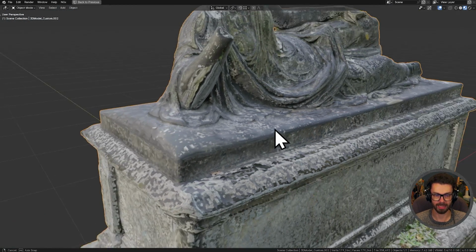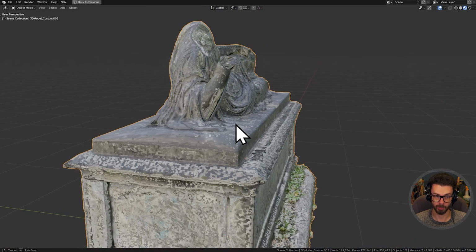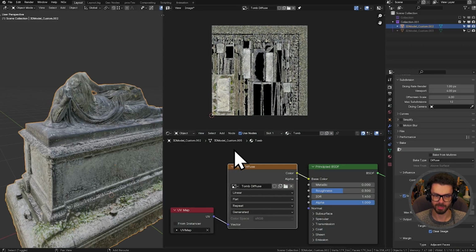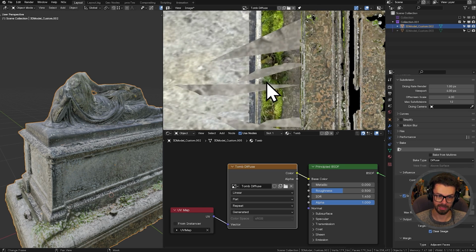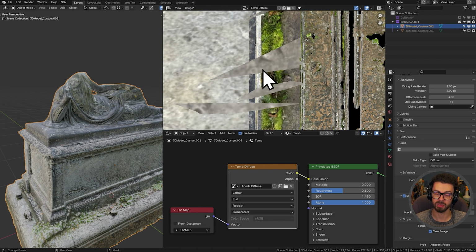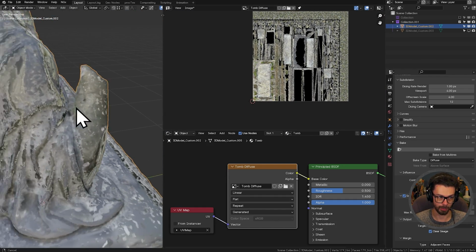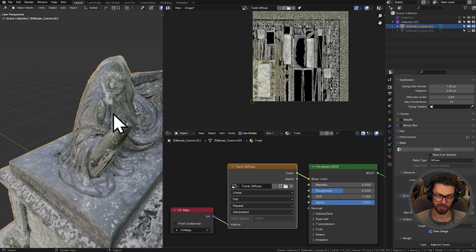And the reason for that is because we tried to bake from 2 separate objects at the same time, sort of in the same space. And what this means is it's not baking from them at the same time. If you watch the progress bar at the bottom while yours is doing it, it will bake one, and then it will bake the next. And technically also what it's doing is it's baking individual mesh islands, one by one by one, and then it will go on to the next one. What this results in is a garbled mess of surface detail.